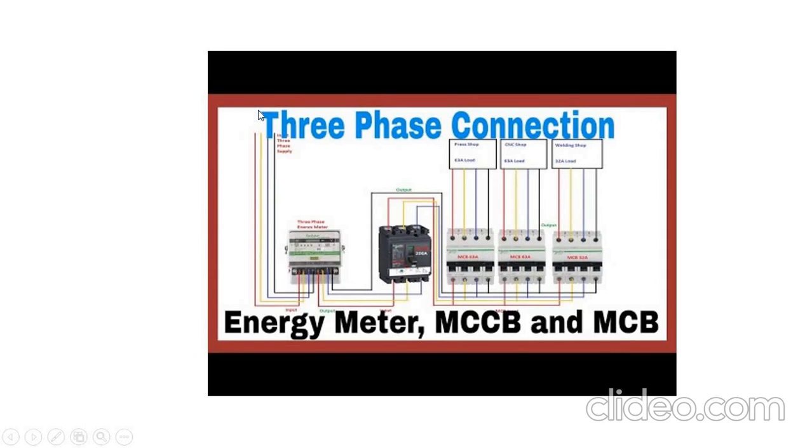As you can see here, we have the main supply. It's going through an electrical meter and then through the MCCB. And then after that, the individual loads are connected to the miniature circuit breakers. So you can clearly see from this demonstration that this is catered for lesser currents, and this is for the heavier currents. So in the case of a fault in any of these loads, the short circuit current is going to pass through this device and also this device. So you're providing double protection for your system and also for your load.